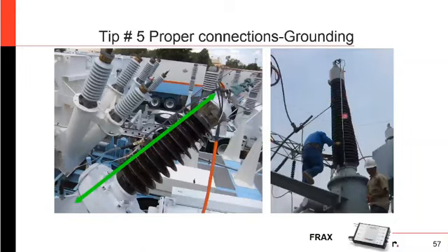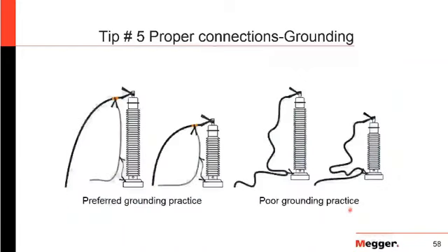Then one thing, and this is always mentioned, typically IEEE recommends doing your winding resistance test last and also demagnetizing after you perform the winding resistance, because an actual magnetized transformer will change the response in those low range frequencies. You've magnetized that core, and it's not going to behave the same since you're just putting a low voltage on there. So make sure that if you do your winding resistance, you demagnetize. But really, before performing winding resistance, you would want to perform this SFRA test, so it doesn't affect the results there.